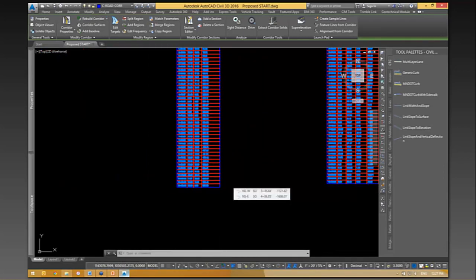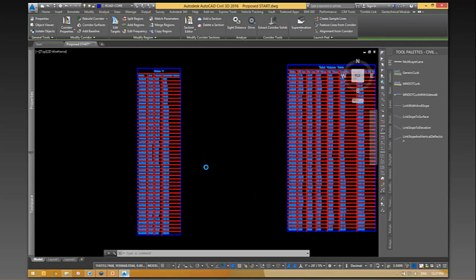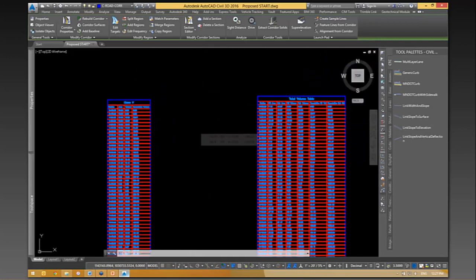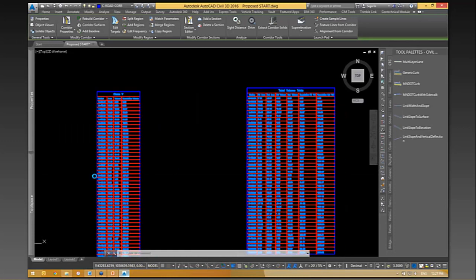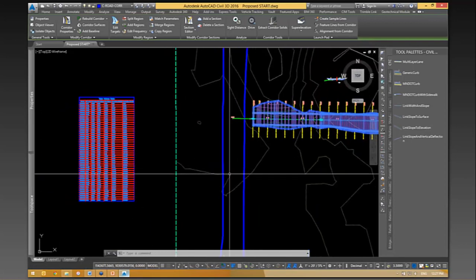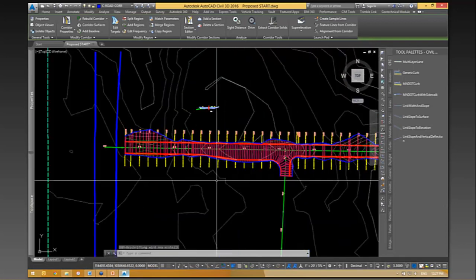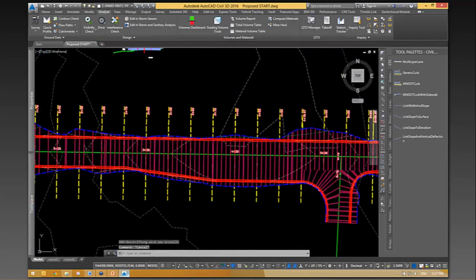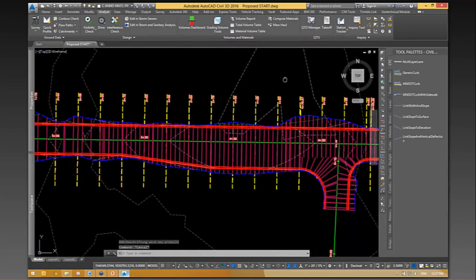Okay, another question came in, can you combine material quantities and earthwork quantities into one table? No, unfortunately you can't. I don't know why you can't do it. I've tried 100 different ways to make it work, short of stacking your tables next to each other and formatting them a certain way, or pushing it all out to Excel. You can't get them in one nice, neat, and tidy table. So, nevertheless, you can get the quantities themselves. All right, that is earthwork or volume quantities.